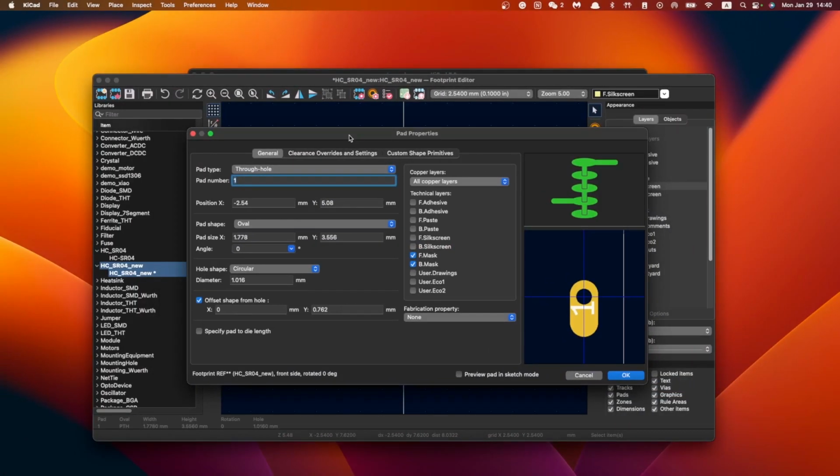real footprint creating thing here. Okay, and one important thing you need to recognize first is that you need to figure out how wide it is between the two pins on this device, right? Because there are 4 pins on it, and you need to know what's the width of those gaps on this device. But fortunately, as I've told you in previous videos, most of these devices are being made to be suitable for attaching to breadboards.